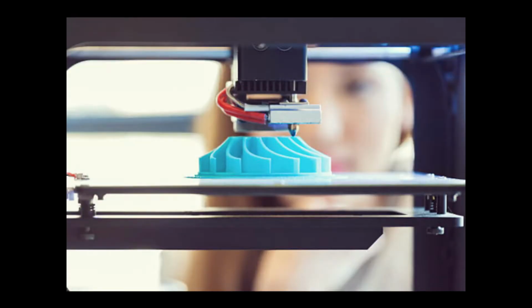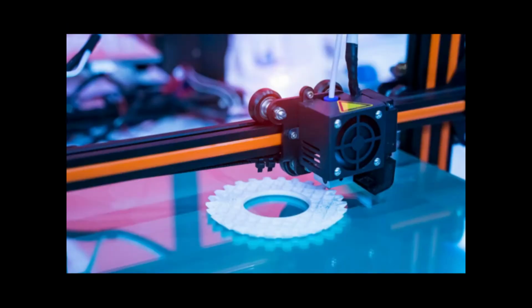Alright, so now that I've explained how 3D printing works and how you do it, I'll go into detail about some of the upgrades that I've done on my own 3D printer. When it comes to 3D printing, there are some basic steps that you must do. For example, you need to have a level bed. Keeping your bed level is important for running a 3D printer. If your bed is not level, your 3D printed plastic will not stick in some places and will peel off the bed plate. This can result in a failed print.